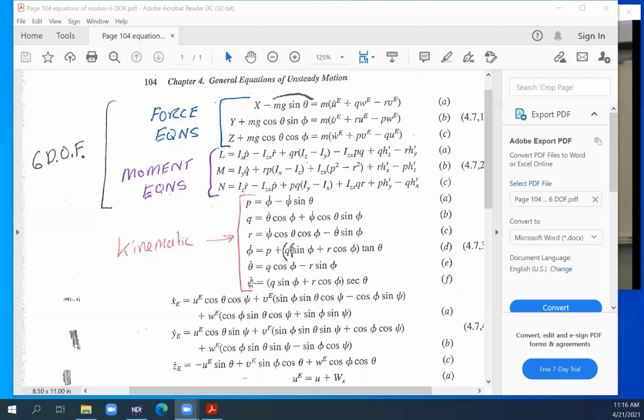P, Q, and R. And we also need to send it forces, right? We've got the aerodynamic forces and so on. Well, what are the forces? What controls this thing? We'd want to send it the aileron, elevator, rudder, and throttle position at the current time. And then inside here, we do all the equations that are then going to tell us the state at the next time step.